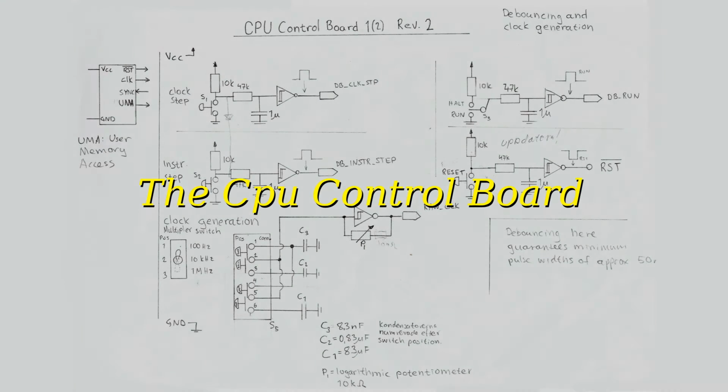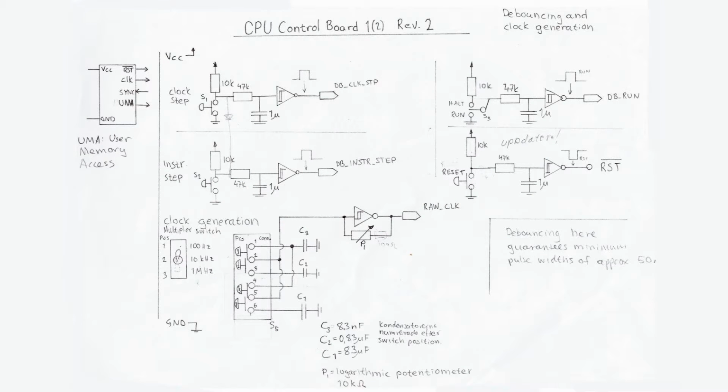Now, let's turn our attention to the CPU control board. The CPU control board is the most complex of all the boards, mostly because of the many switches and buttons. It is divided into 2 different sheets, and this is the first one. The clock and instruction step buttons are debounced and the signal is sent off to the next sheet. The run halt switch and the reset button are treated in the same way.